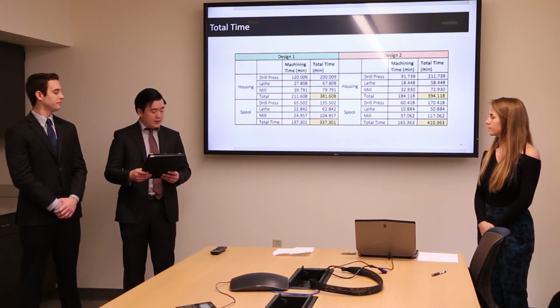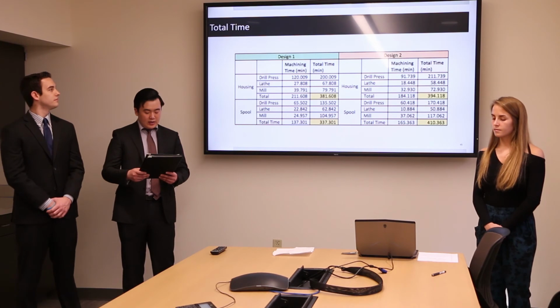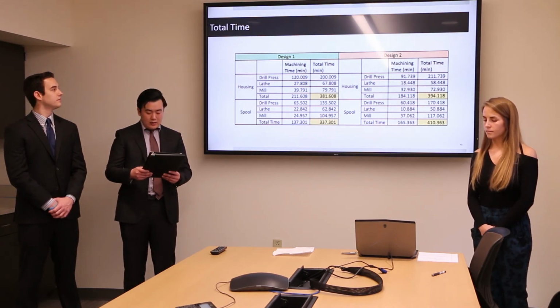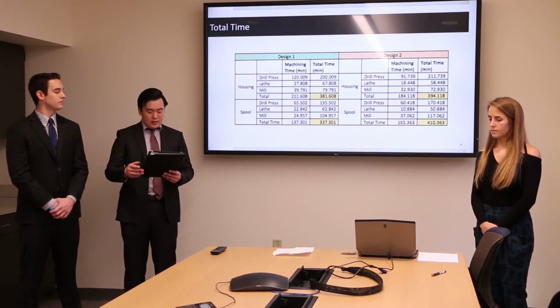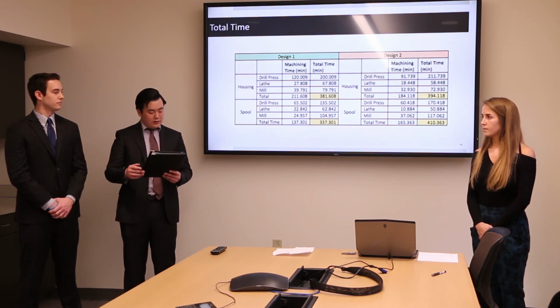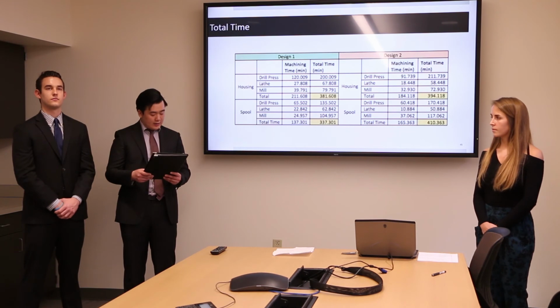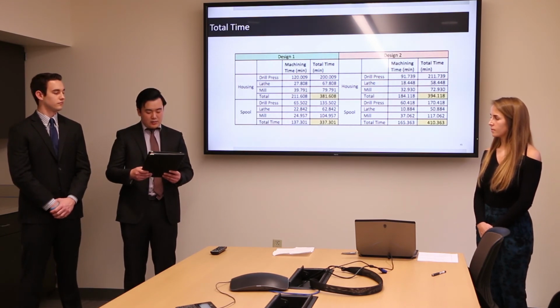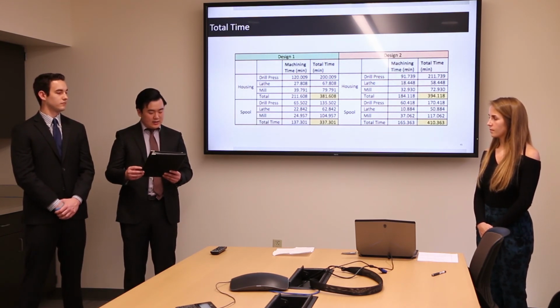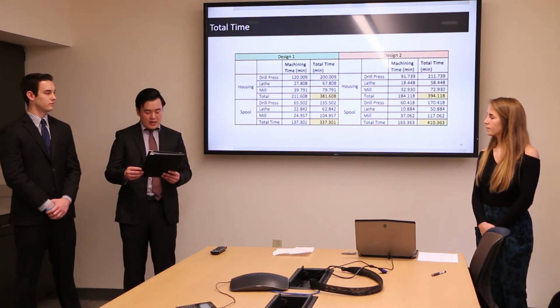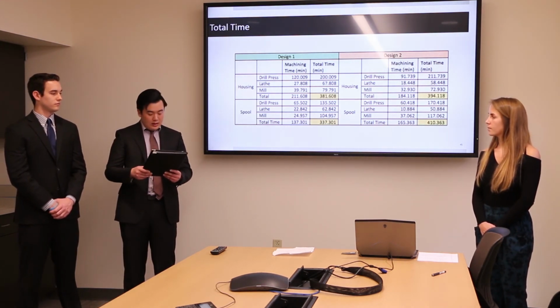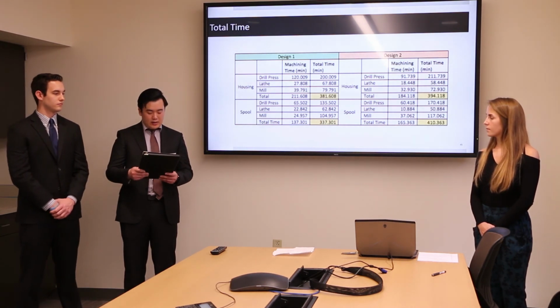For both design 1 and design 2, from this chart we can tell that comparing to design 1, the mold machining time actually increased slightly. However, the increase of mold manufacturing time is a fair trade for the decrease of total cost. Since design 2's injection molding thickness is way less than that in design 1, the cooling time, also the injection molding time, is greatly reduced, as the chart in the process plan indicated.